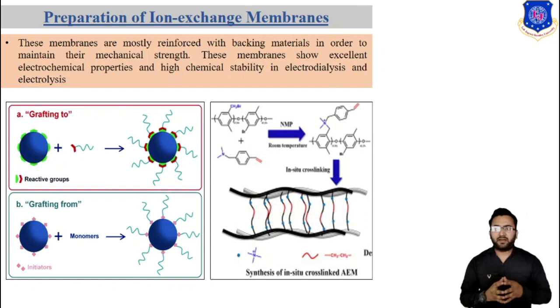In general, when an ion exchange membrane is made by this method, the exchange groups are distributed heterogeneously across the membrane cross section. Another method is the direct introduction of cation or anion exchange groups into a conventional polymer such as polyether sulfone, polyethylene oxide, polyvinyl chloride, and so on. The method to make the anion exchange membrane an anisotropic structure is to form a highly cross-linked layer of anion exchange membrane over a porous vinyl fluoride membrane. The membrane made by this method is suitable for diffusion dialysis.